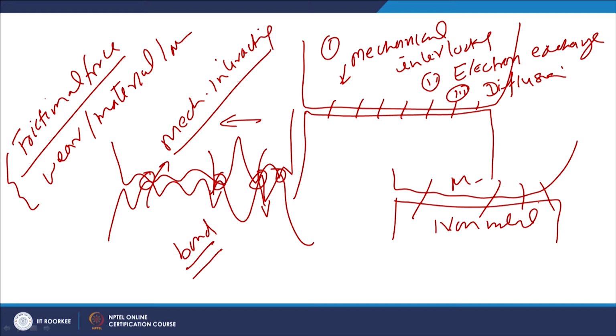So, it is always good to have a situation where, out of the two metals, they are reinforced with non-metallic constituents. Wherever the non-metallic constituents are present, such free electron exchange will not be possible across the interface. So, the bond formation tendency is reduced.